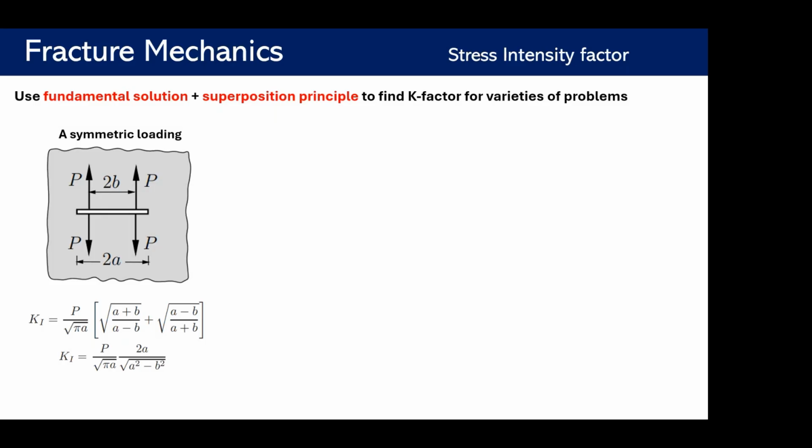So I should combine the far and near fundamental solutions together to find the stress intensity factor at the right tip. But as the problem is symmetrical, the final result should be the same for the right and left. So by combining the fundamental solutions for the near and far tips, we find the stress intensity factor for the symmetrical problem. Any question?